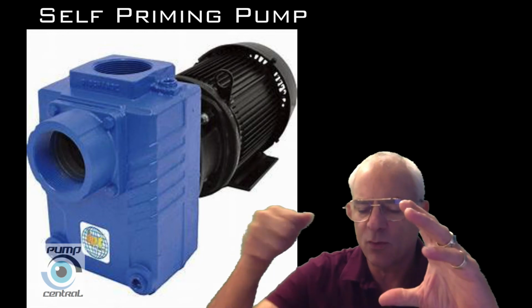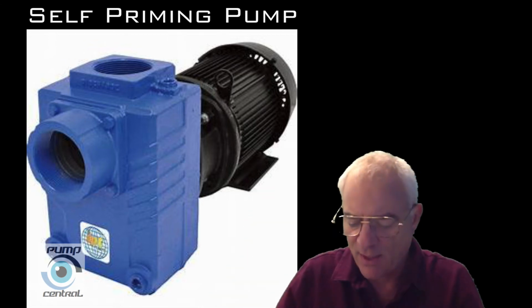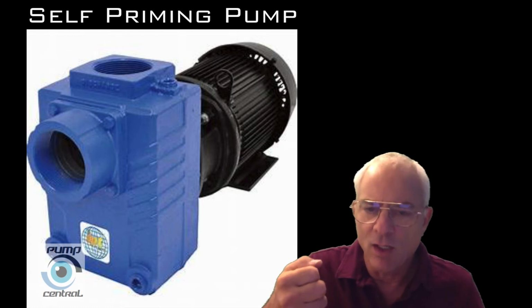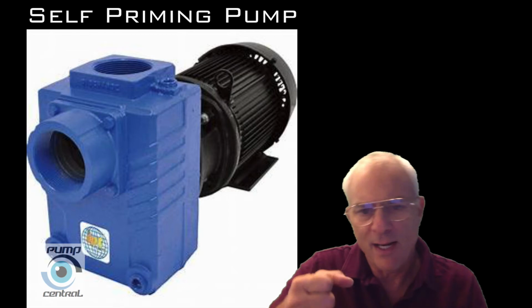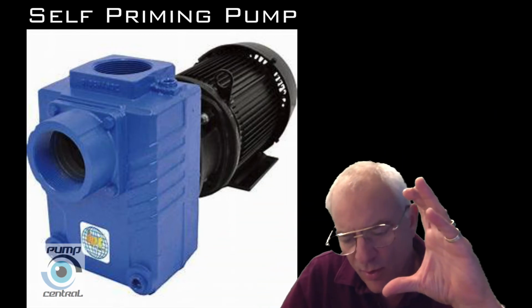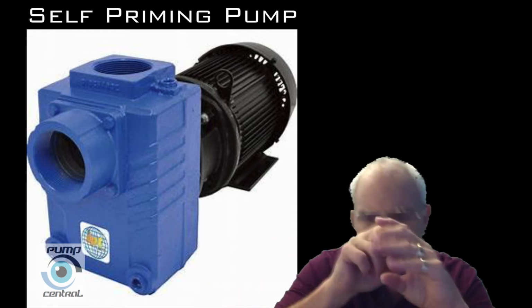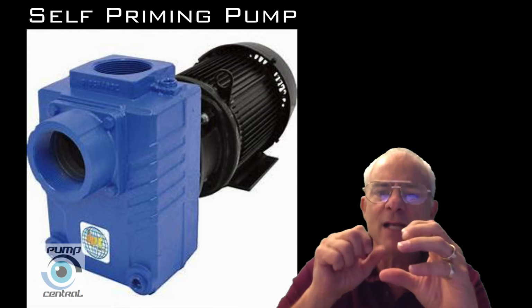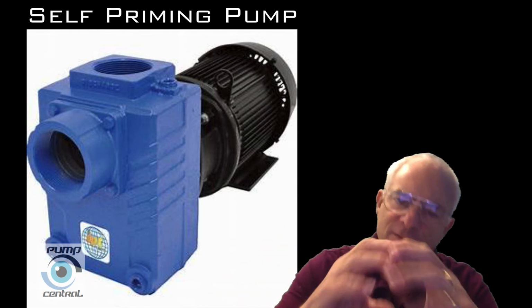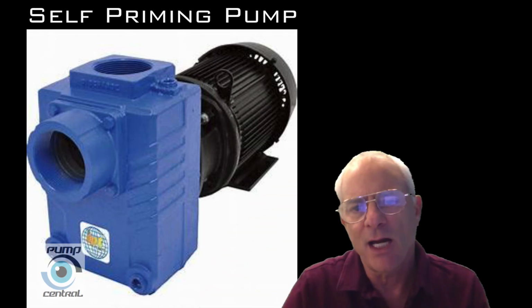So they can start with, say, a pipe that goes down 10 feet into a tank or something and has what we call a check valve on the bottom, a foot valve, that allows water to only go one way. And that pump will start forcing the air out very slowly, but it will create a vacuum until that water gets pulled up into the pump. And then it will force that air out once the water comes and fills the impeller, and it can expel the air.